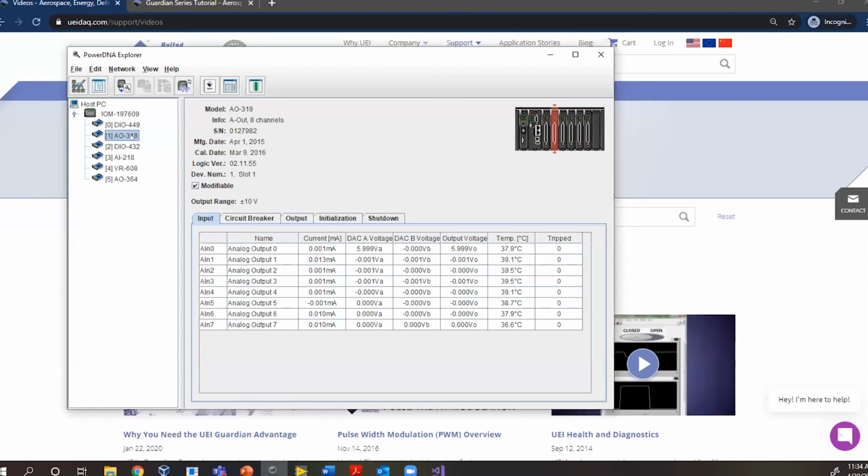So you're outputting this voltage, but almost as a double check, you verify that that voltage is occurring. If we try to output 6 volts, we better measure that it's 6 volts. And if it's not, then we know there's an issue. If we output 6 volts and there's no current, then again, we know there's an issue.